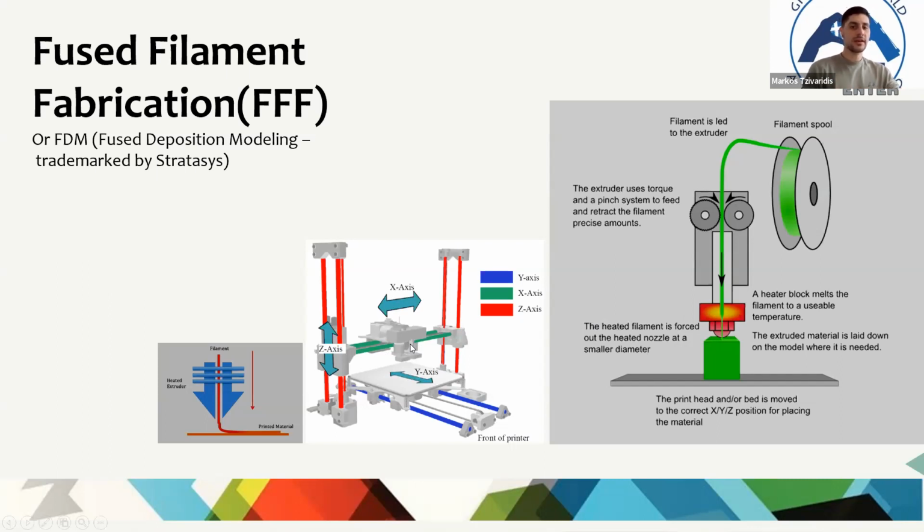And the melted material is extruded in thin strands, and it is deposited layer by layer while it cools and solidifies. So let's say that these are the layers, and this part here is already solidified because it cools at normal temperatures. Sometimes the cooling of the material is accelerated through the use of cooling fans. You will see the cooling fans in the video after this.